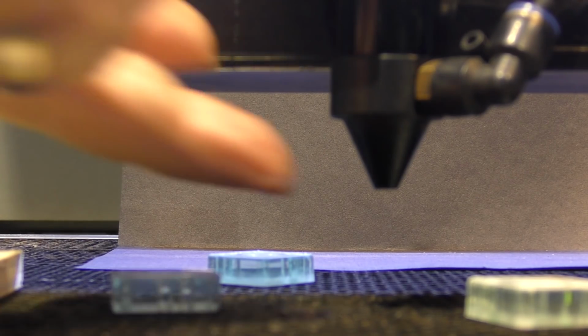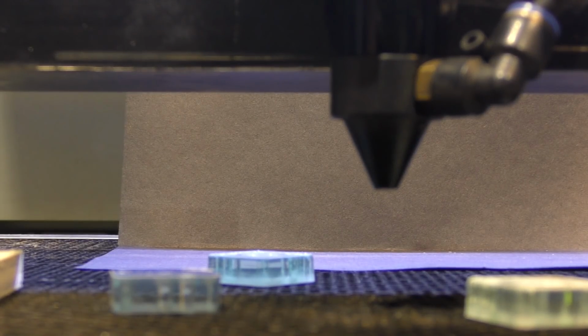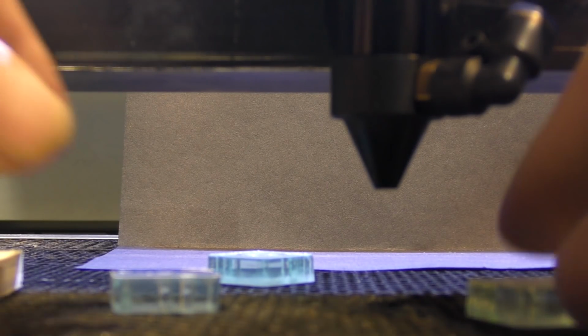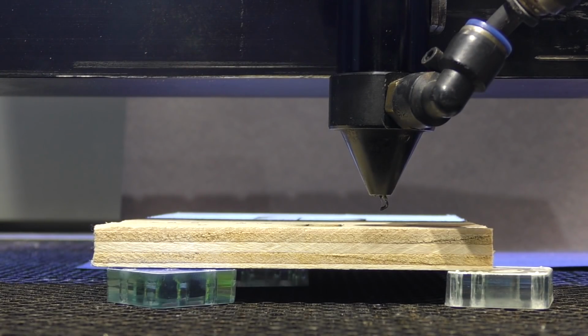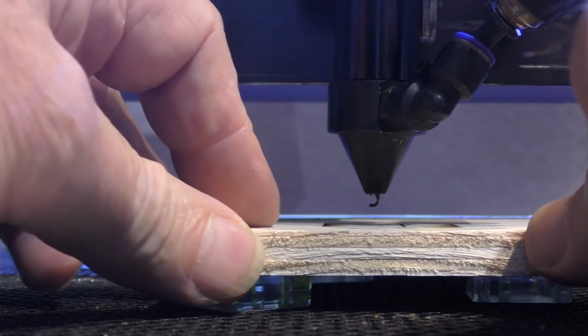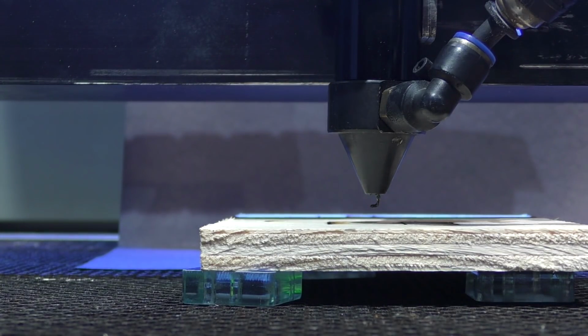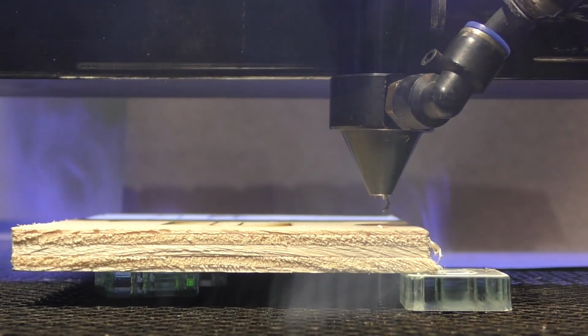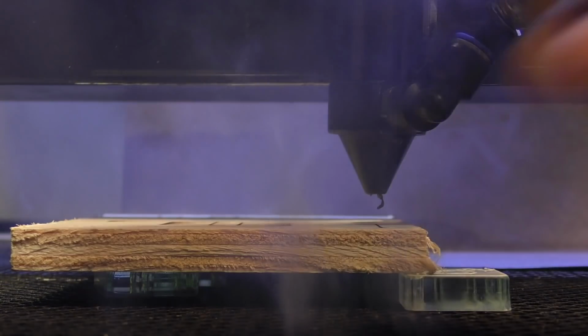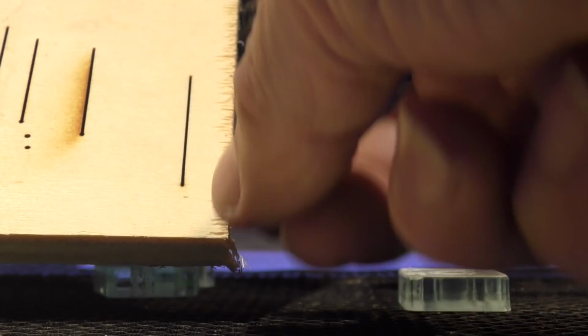First of all, because it's restricted, you can hardly hear the pulsing. It's another piece of physics which I'm not going to go into. Let's just see what difference this has. Remember that smoke that is busy absorbing your energy because it's coming up? We're pushing the smoke down as fast as it's being produced. We're not allowing it to go near the raw, lovely, new, naked laser beam. It's being blown away from the laser beam. And there we go, a lovely clean cut.